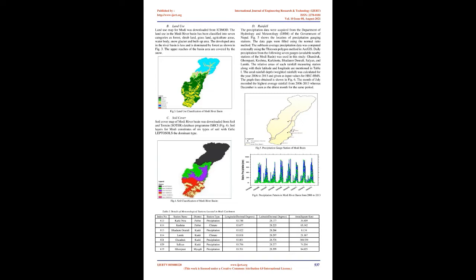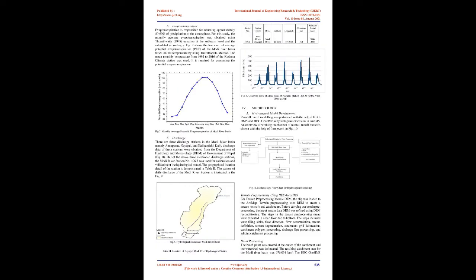Several applications of the HEC-RAS model to determine the extent of inundation resulting from a given flood have been reported. 12, 13, 14 applied the HEC-RAS model to calculate water surface profiles corresponding to selected flood events downstream of Al Wada Dam in Seba Basin in northern Morocco. Software often used in combination with HEC-RAS is ArcGIS. It comprises a set of tools, utilities, and procedures for working with geospatial data. The basic inputs to HEC-RAS include the river discharge, channel, floodplain geometry, and channel resistance.